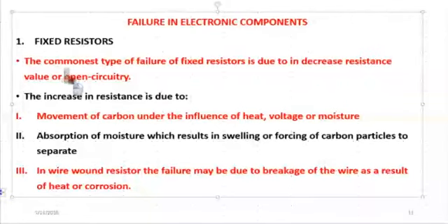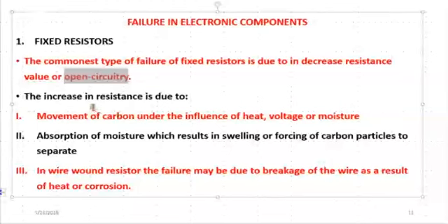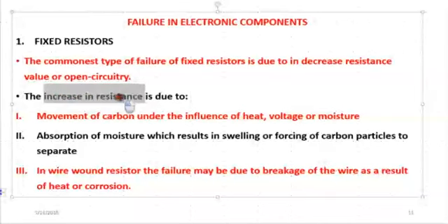Another kind of failure that is common to the fixed resistors is open circuitry, in such a way that it will not have connection between one point and another. Therefore, the resistance between the two terminals should be infinite, which makes the resistor useless. And there is another problem of increase in resistance. What brings about it are these items.